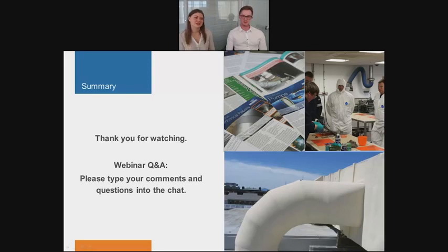The highest temperature that Belzona products can tolerate? The highest temperature product coating-wise that we have goes to about 160 Celsius. And that's Belzona 1593. Normally, that's not used in a lot of the applications we see with heat exchangers, HVAC systems. It's usually down the lower end, so we're talking less than 100 degrees. But yeah, 160 C is the highest we recommend.